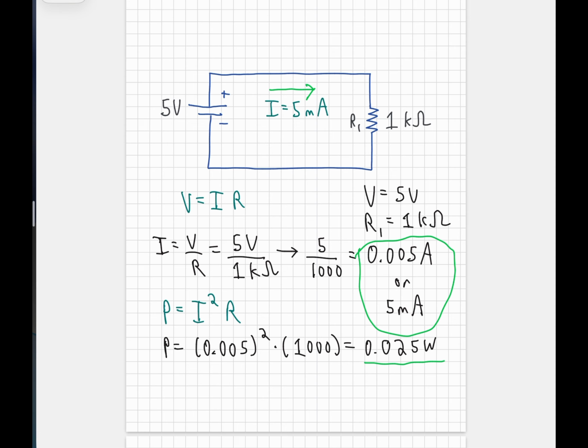So now we know how much energy we're using up every second, or how many watts we're using. We want to make sure that this system is balanced. We want to make sure that the energy being used up here is the same energy being supplied by the source, which is right here. And there happens to be a formula for that also. This is for the voltage source now. I'll say power for R1, but this power for the voltage source is negative V times I.